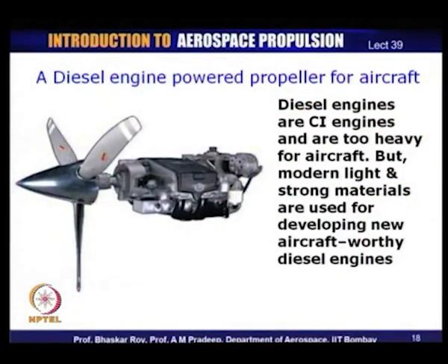Fundamentally, the CI engine is heavier, as a result of which it was never considered very seriously for aircraft application. However, in recent years, CI engines have again been considered, and one of the reasons is that they can now be made of modern, light and strong material, which can withstand the high pressures created inside the cylinder, and hence you can use CI engines, the diesel engines. These are known to be thermally more efficient devices than engines using normal aviation fuel in piston engines of aircraft.